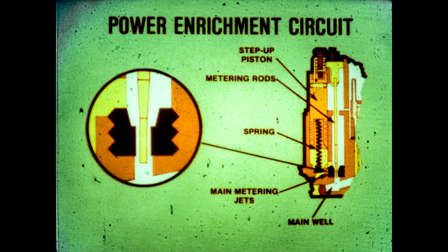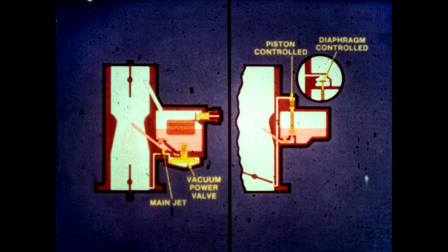When the throttle is at cruise, manifold vacuum stabilizes, allowing the metering rods to pull down to the proper point for the throttle opening. In most applications, a mechanical linkage positions the metering rods for the throttle opening. Vacuum further adjusts metering rod position in response to engine load.